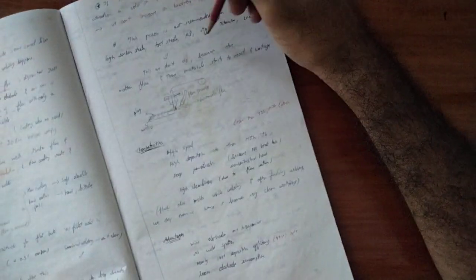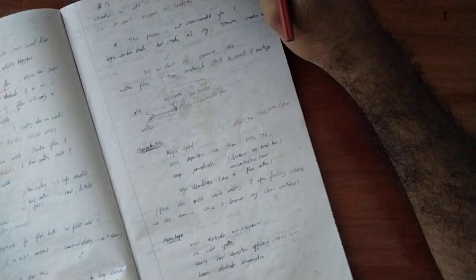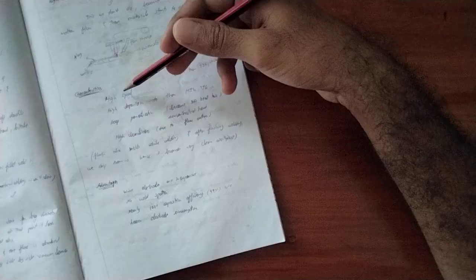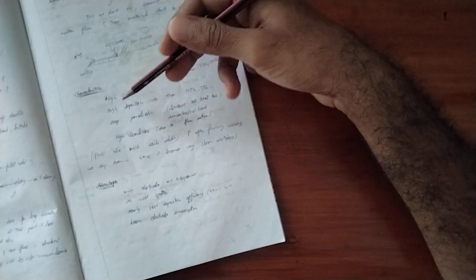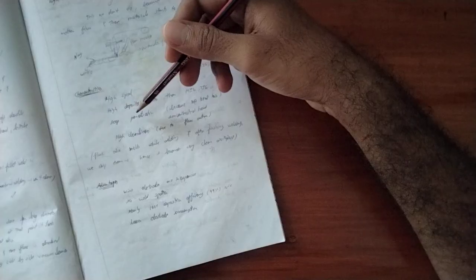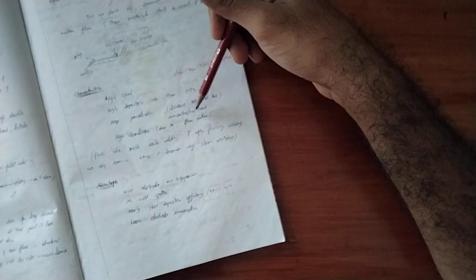This we don't use because more molten flux and metal starts to react and wastage will start to occur. Okay, next one is it is cleaner than tungsten inert gas and metal inert gas welding. Next, characteristics: high speed and high deposition rate, then big, thick and deep penetration because there is no heat loss and the heat is concentrated, and high cleanliness due to flux action.